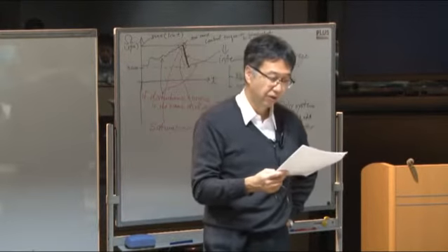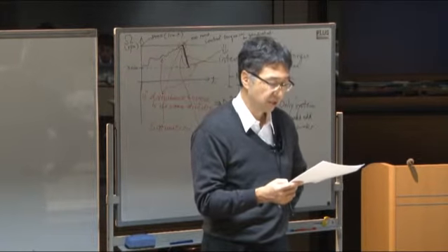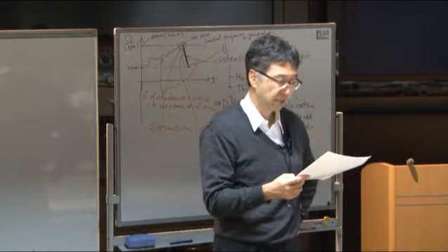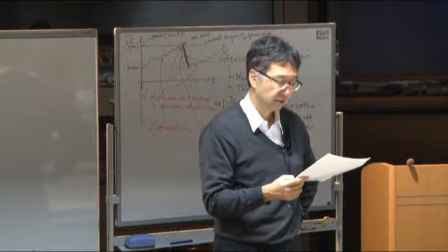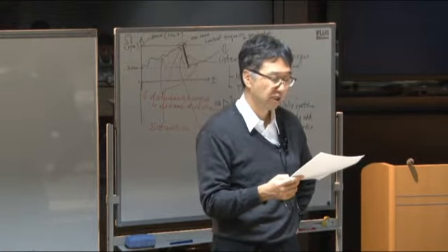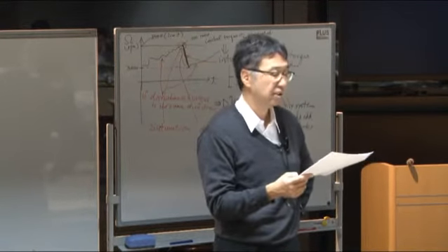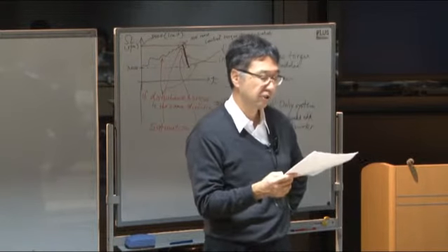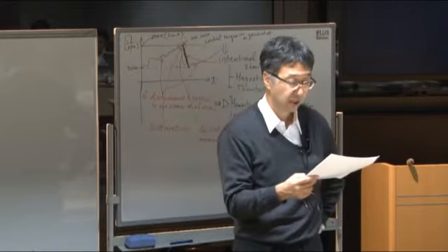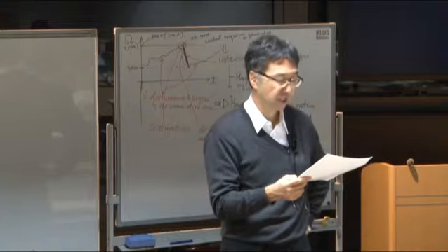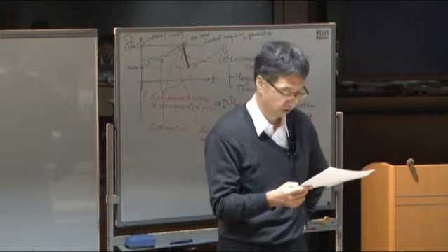Okay, so the number 4 is an example of the disturbance torques. Almost all of them I already showed you. The first one is astrodynamic. What is astrodynamic? Astrodynamic is gravitation from the third body. The third body means not the Earth. For example, the gravitation from the sun or the moon. But this disturbance torque does not have an effect on the attitude. It only affects the position.